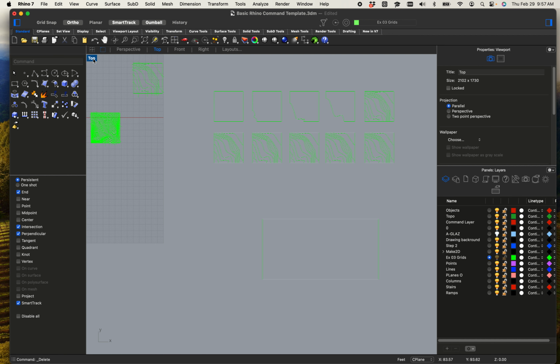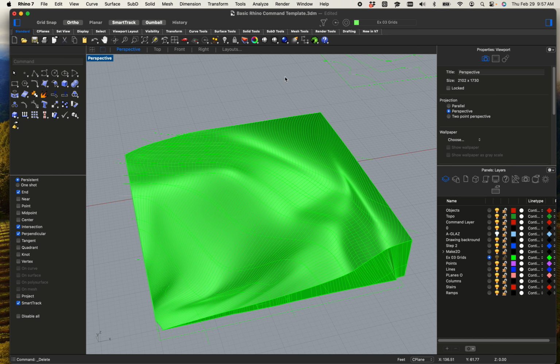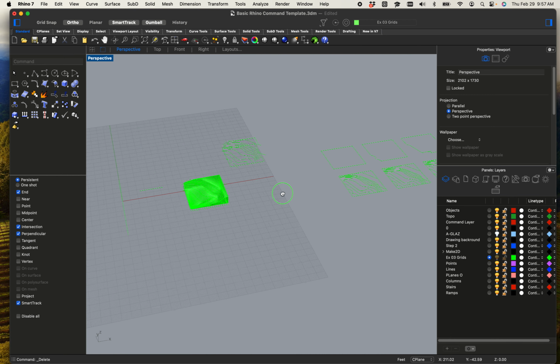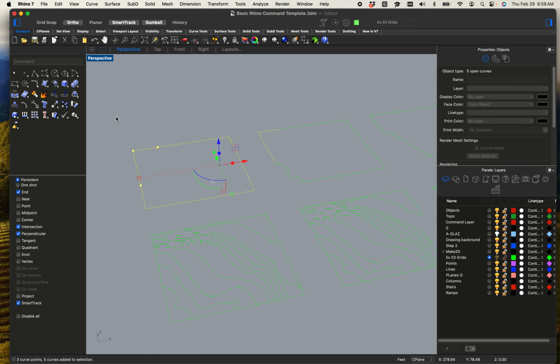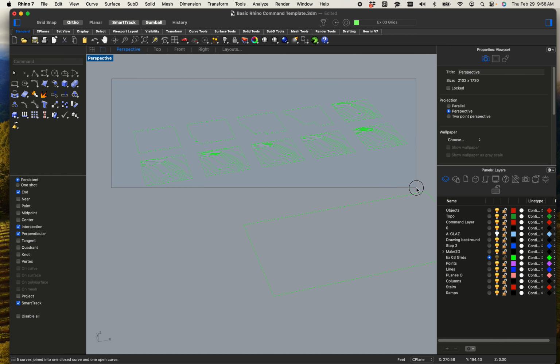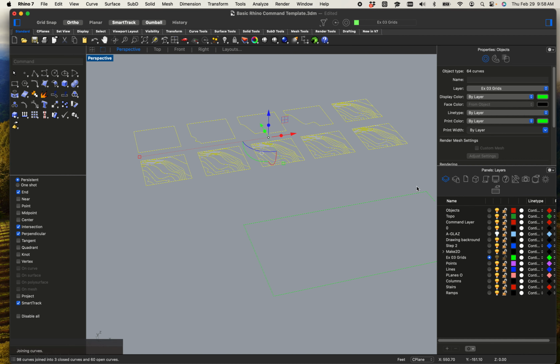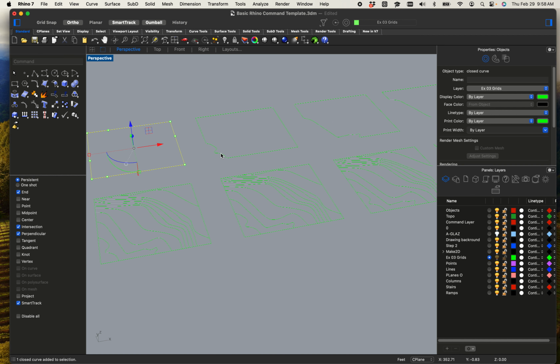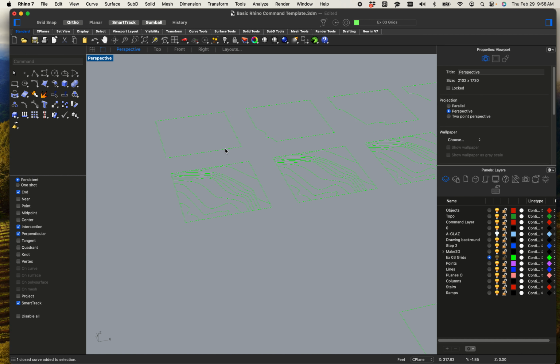But lastly, I do want to show you another way of modeling it, just in case, again, that loft method just might not work for you. You might have a different situation. So I wanted to show you that you can also, of course, extrude these things, right? So I'm going to join them. And in fact, join works no matter what. As long as lines are touching, you can select everything and hit join. If it's not touching, it won't join. So it's going to join that for me, join that for me. And again, I'm working smarter rather than harder.